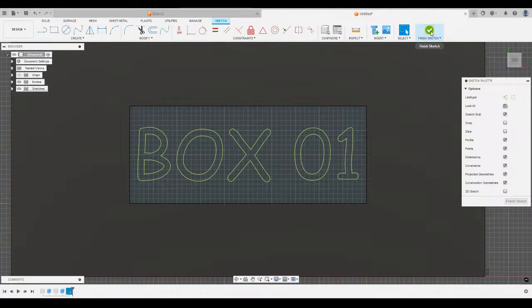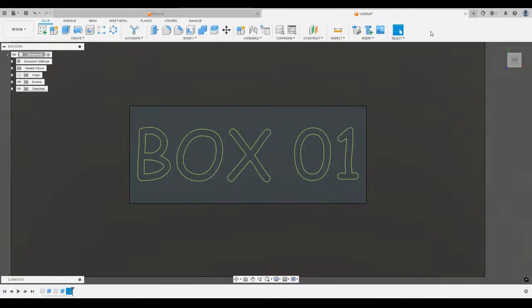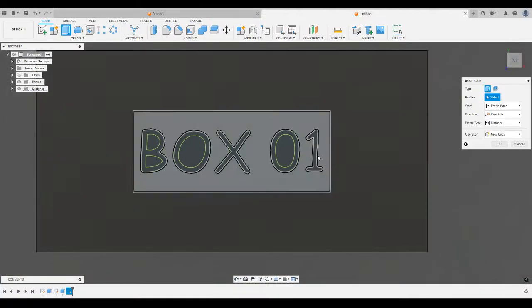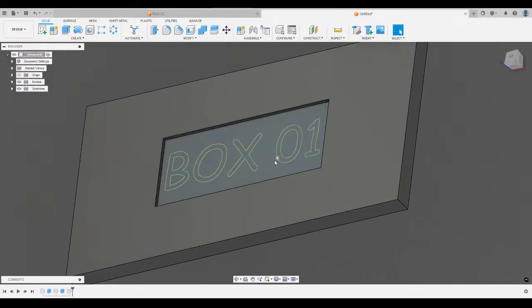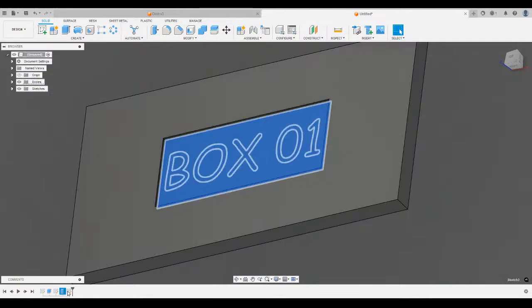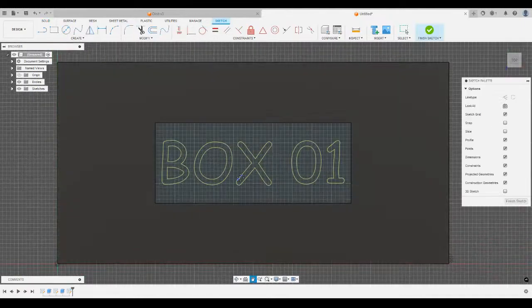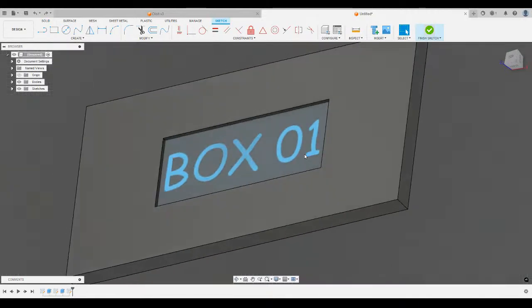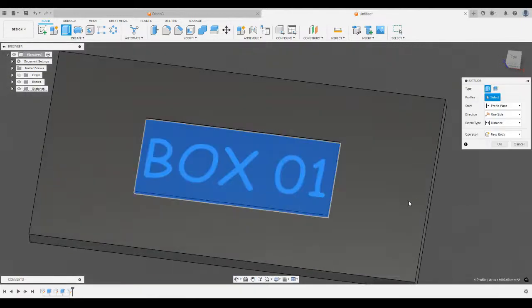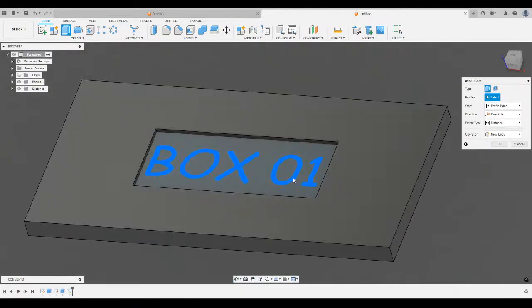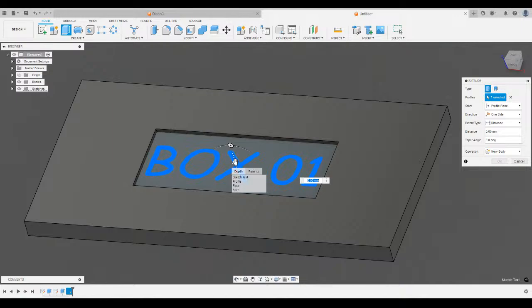So previously in Fusion, you had to do that in order to do anything three-dimensional with it, to select it and extrude with it. But the catch was that once you explode your text, you can't edit it without undoing it. But it looks like at some point, I had no idea they added this. They changed it, so now you can select it.